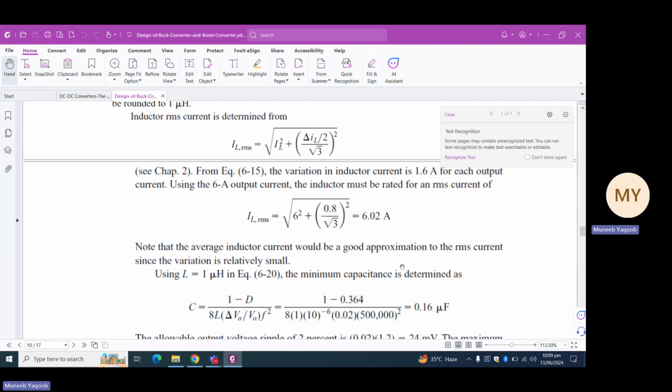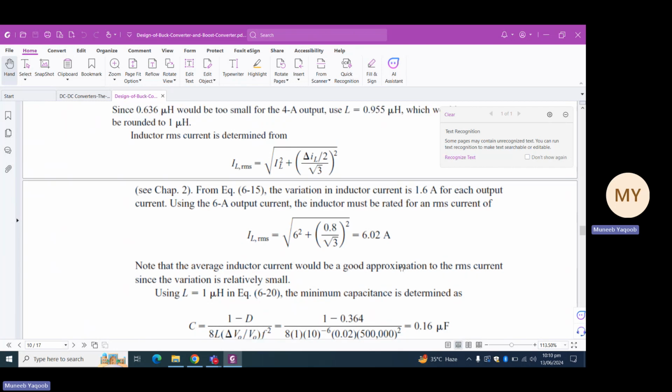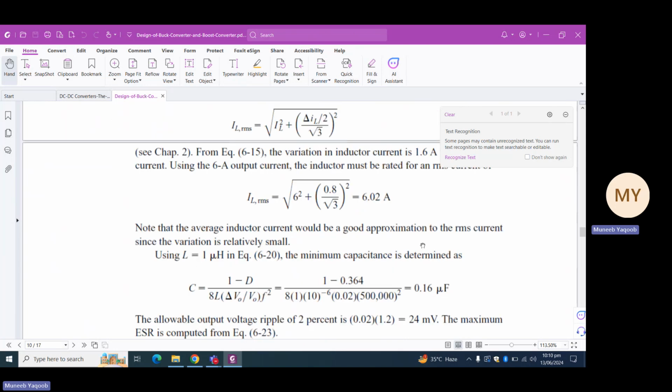So that was basically the calculation or the design of a buck converter. You must know that when we say design, we are to calculate the values of capacitor, inductor, and even if the resistor is not given, then we are to provide those values of capacitors, inductors, and resistors that meet our design criteria. That is, they fulfill the minimum and the maximum current specifications. They fulfill the deviations, that is the delta IL conditions that are given in the question.